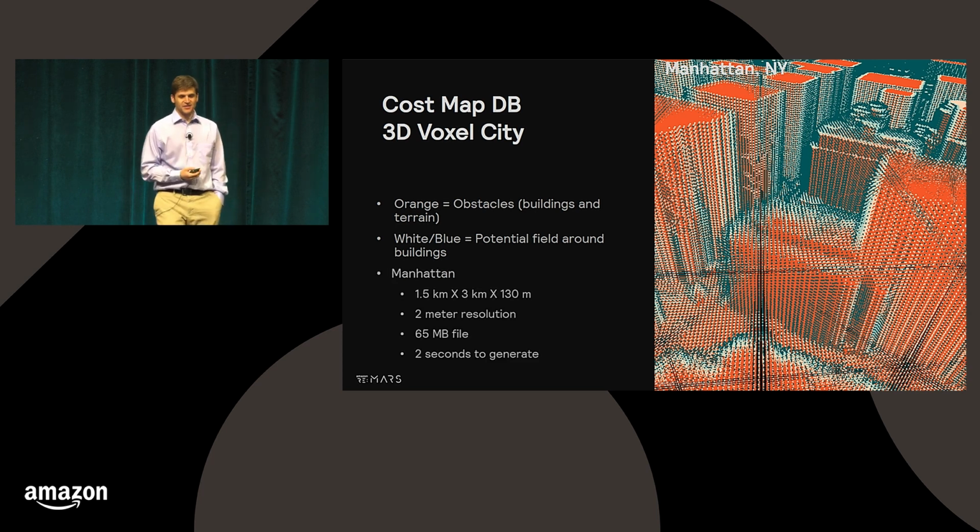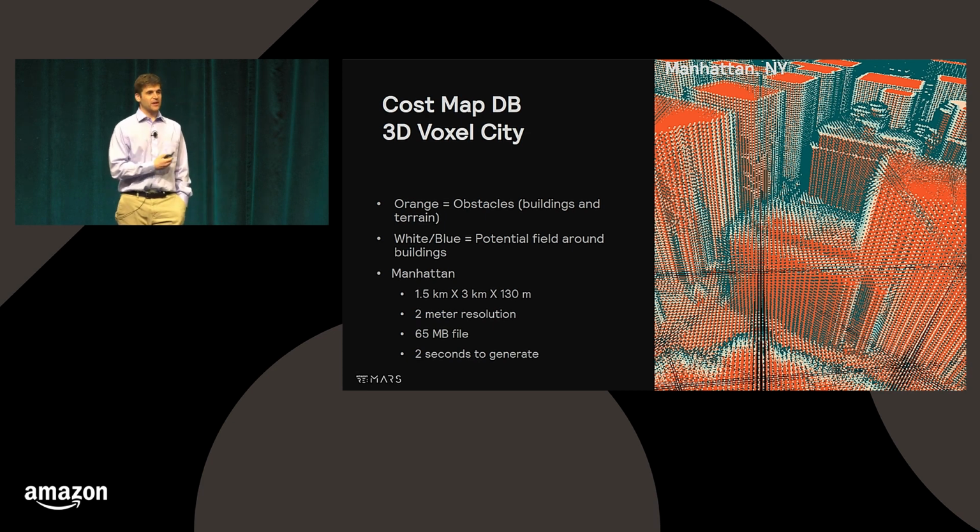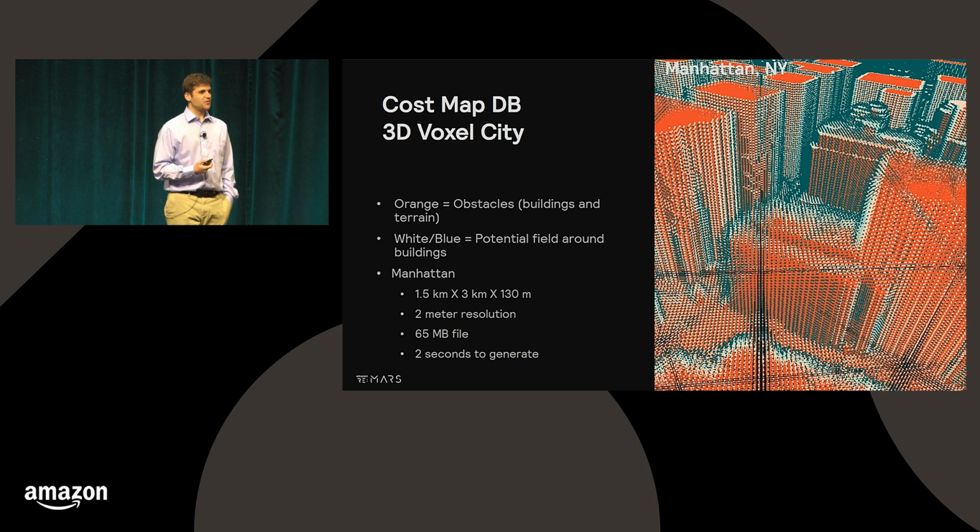So this is Manhattan. This is a huge map, about 1.5 kilometers by 3 kilometers, 130 meters tall, with 2-meter resolution for the grid cells, and it's about a 65 megabyte file, which can be easily put on board and used in path planning if needed. There's definitely lots of improvement that can be done for compression, whether using octrees and so forth.